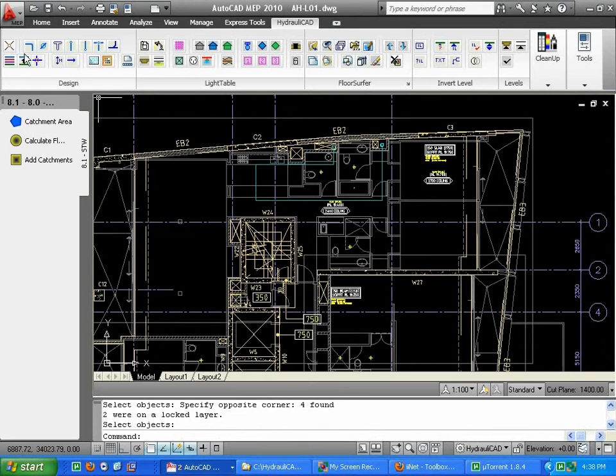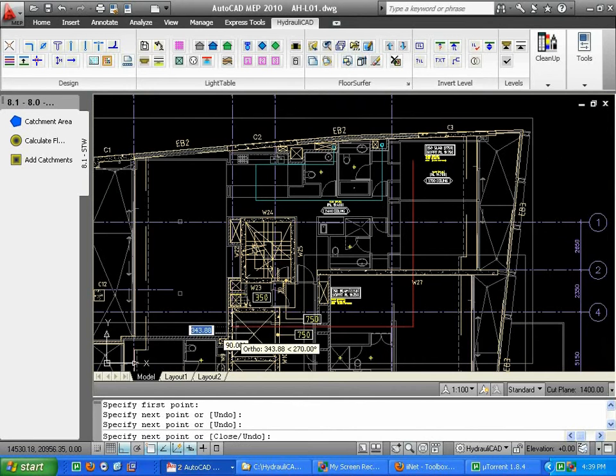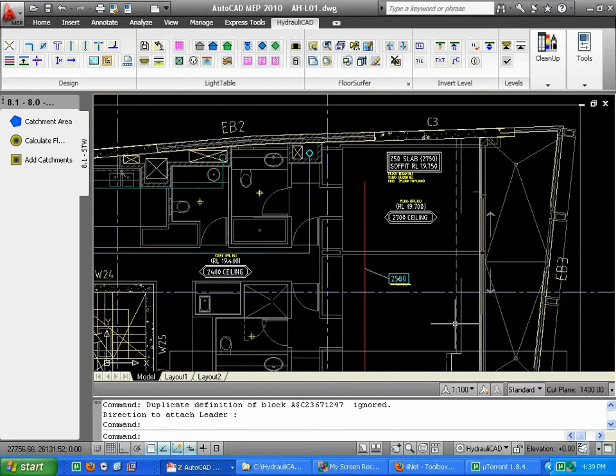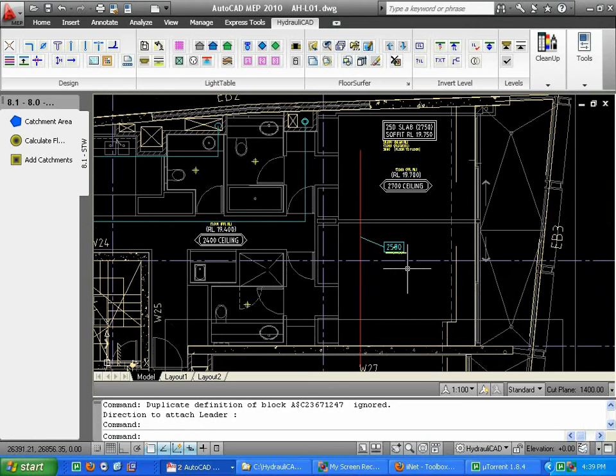If we also had a fire hydrant pipe running down here, and we just wanted to put an invert with no fall on it, we could put in a height. So we could say start invert level, and we just want to put in a height, 0 grade, pipe OD is 120, support spacing, we'll keep it at 50, and our soffit, and then we just put in a height there. So we can quickly put in heights on pressure pipes as well.